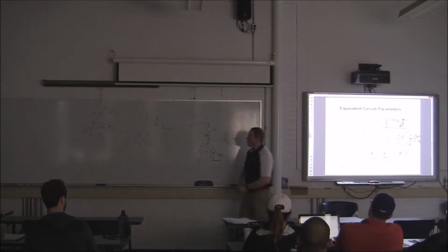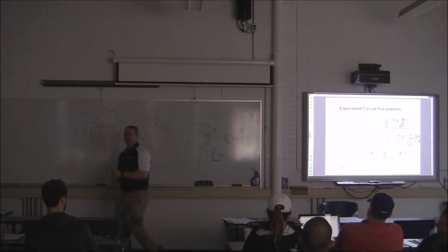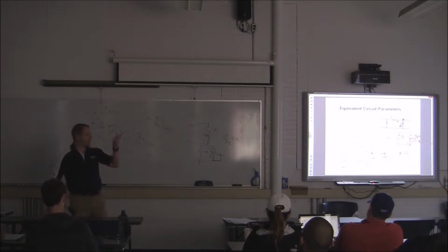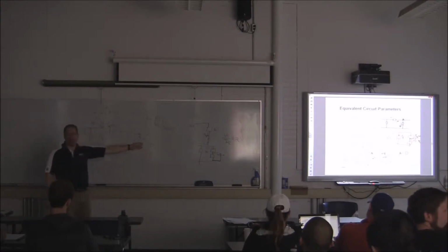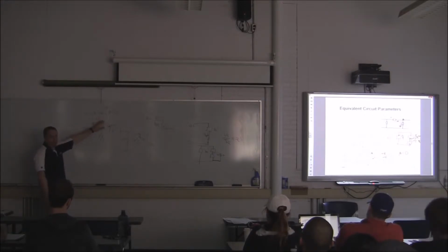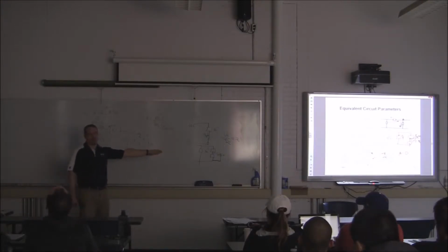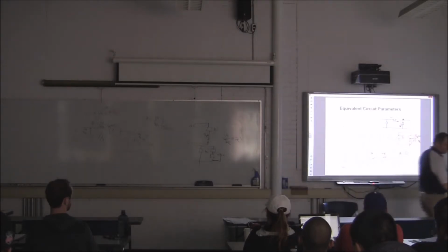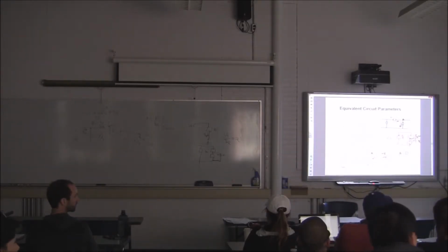So you can do the two-port parameter approach instead of doing circuit analysis and saying, let's do Kirchhoff's current law, nodal analysis in the original circuit. Usually you can simplify your circuits down quite a bit by recognizing, hey, let me get rid of B or let me get rid of A and then solve the rest of the parameters. In either case, you're either going to put an open circuit or a short circuit, and that'll take care of it.